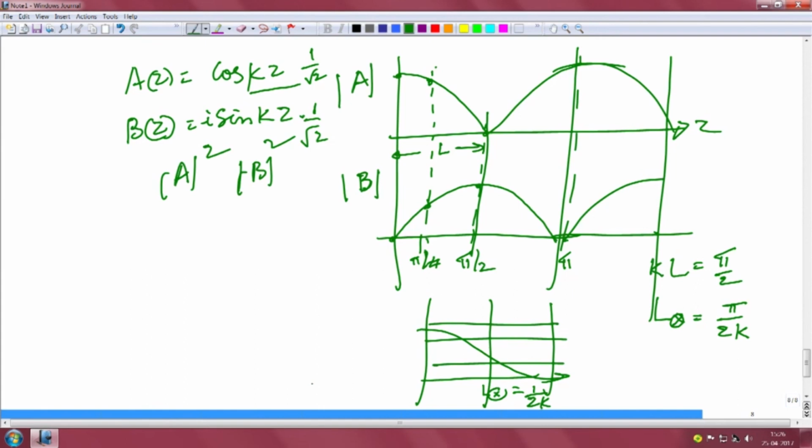So, in conclusion, we can say that directional coupler is a very useful device. I would just like to mention that in optical switches we can change the delta in the refractive index by using external fields, and we can switch between the crossover state and the bar state by using external electric fields. We will come over to these after a few more classes. So, finally, to summarize, directional coupler is a device that can be used to exchange power between waveguides, and there are many applications.